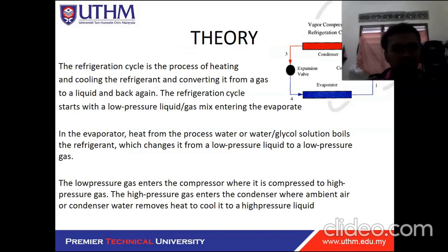So for the theory, the refrigeration cycle is the process of heating and cooling the refrigerant and converting it from gas to a liquid and back again. The refrigeration cycle starts with an appropriate pressure liquid or gas mix entering the evaporator. In the evaporator, the heat from the process water or water glycol solution boils the refrigerant, which changes it from low pressure liquid to a low pressure gas.